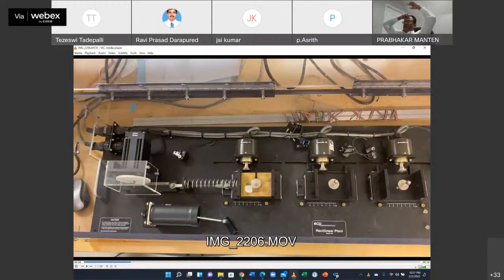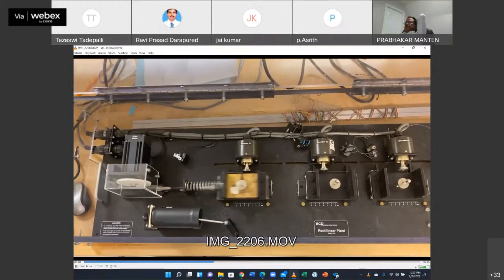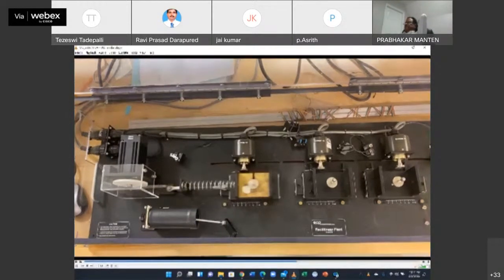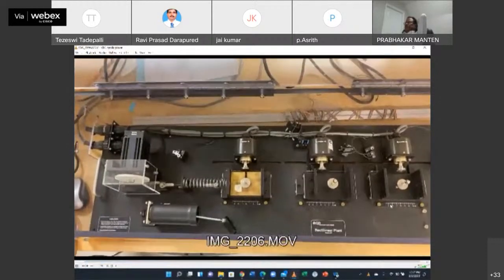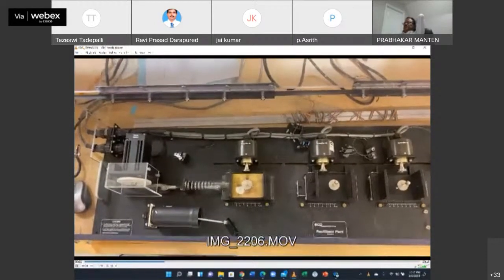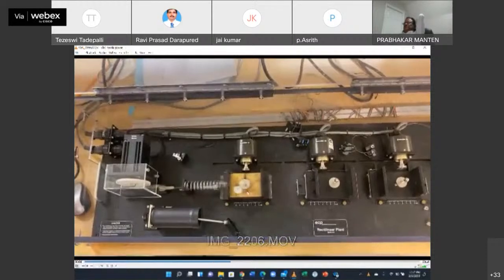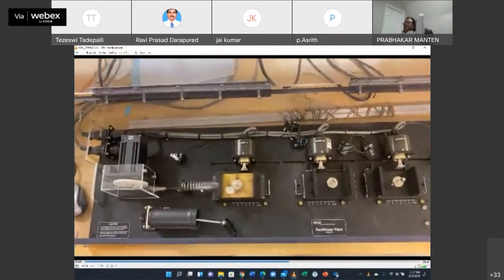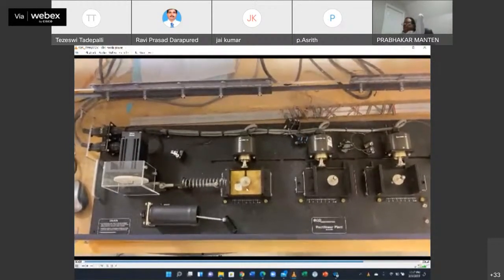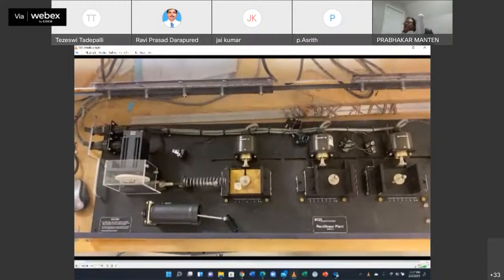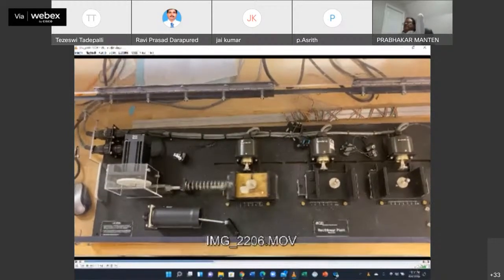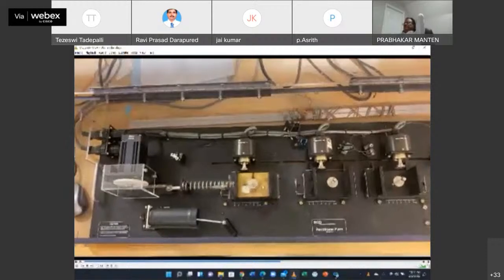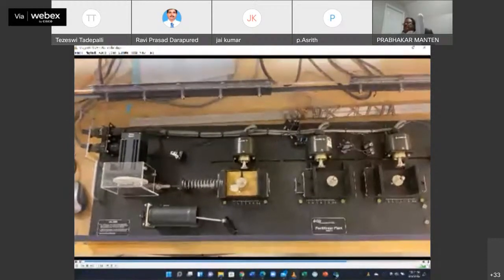Okay, this is in our lab. We make the students do a single degree of freedom system. We have up to 3 masses, springs, and dampers that can be moved wherever you want. We subject it to a forcing frequency. Theoretically, students calculate the mass and the stiffness of the spring, all known data, and calculate the natural frequency and force this generator to force that. So you see, in a fundamental mode, this is straightforward, right? Back and forth, exactly whatever we calculated.